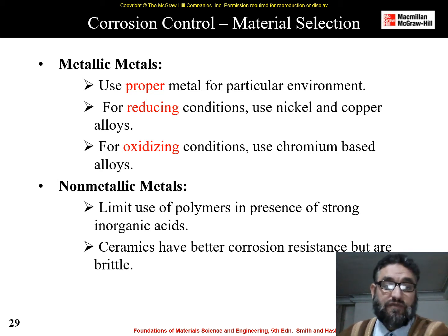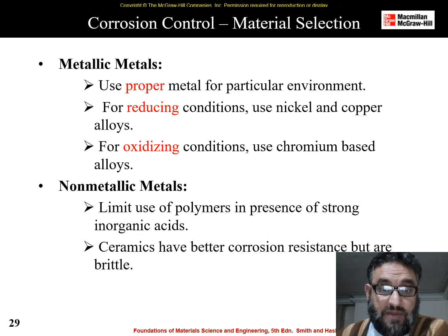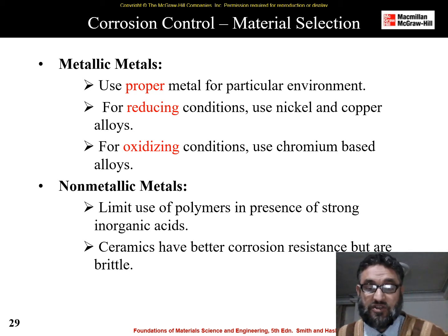Secondly, if the materials are non-metallic, limit the use of polymers in the presence of strong inorganic acids. We can use ceramics also, for better corrosion resistance, but ceramics has a disadvantage because it is brittle and sometimes it doesn't meet our functional requirements.